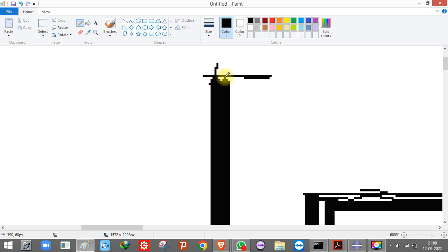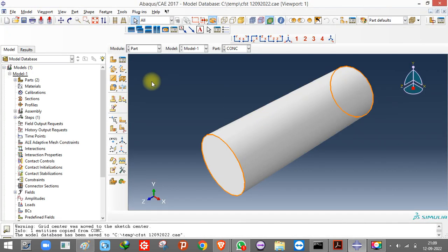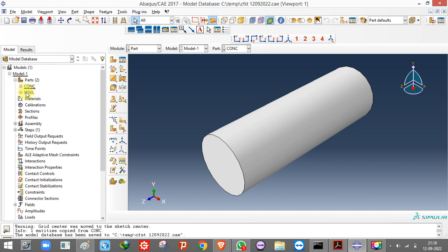Concrete takes the load a little bit later, because the top portion of the concrete is not that accurately placed. If you do not consider that, I have found from my experience that the modeling result is not accurate, failure and all.